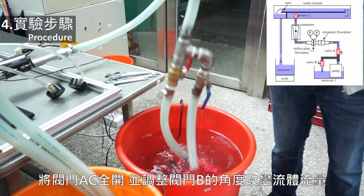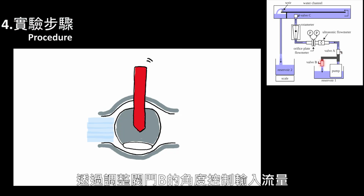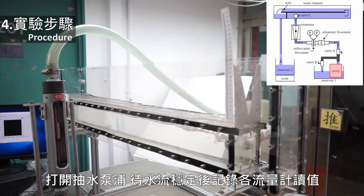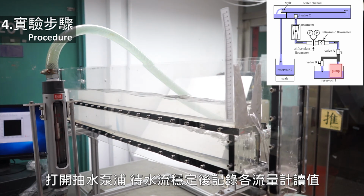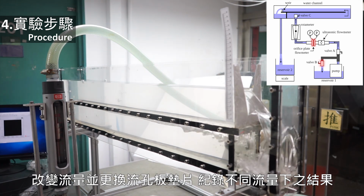Fully open the valve A and valve C. And adjust the valve B to produce different flow rates. Turn on the pump. Wait until the system reaches steady state, and record the readings from each flow meter. Then change the flow rate and orifice plate, and observe the difference.